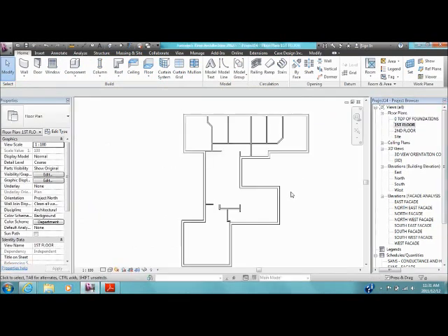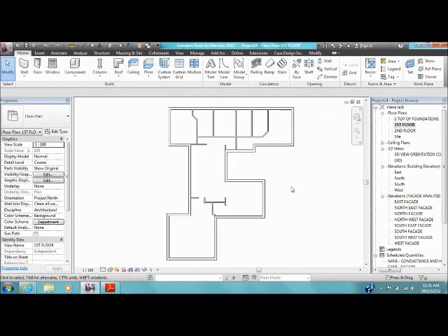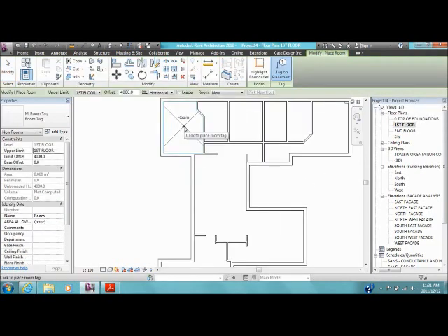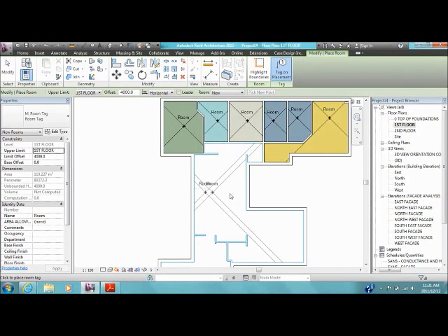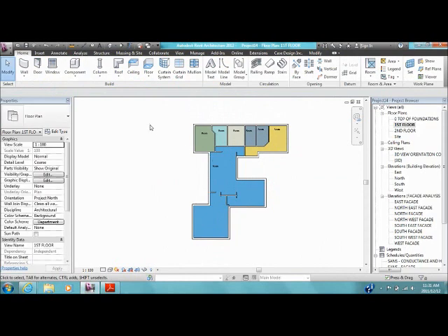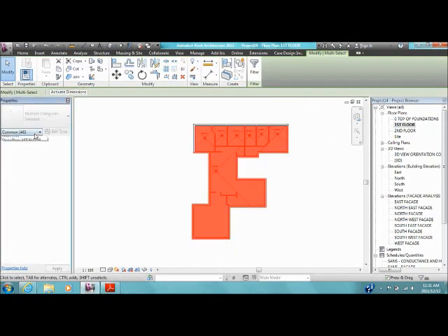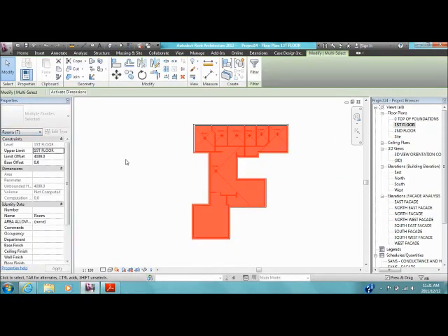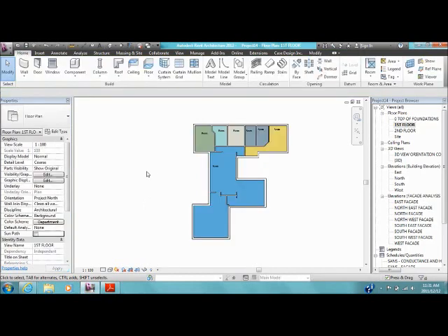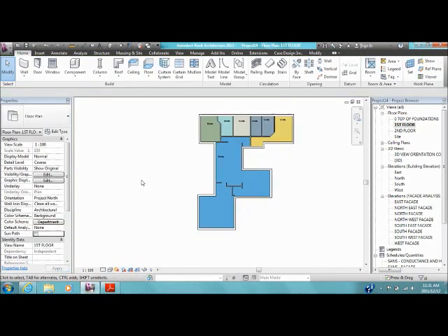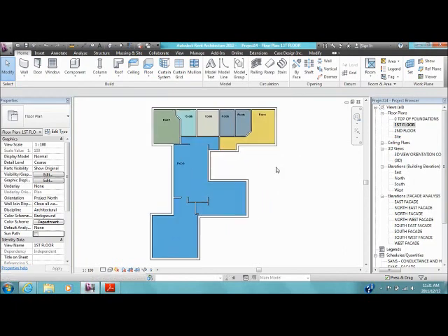Now, what I need to do first and foremost is do the calculations for the area-based allowance, in other words, for naturally ventilated buildings. I don't have to manually click in the corners of the areas to define my rooms. I can simply use Revit's automated tool. What I do need to do is tell it which zone these rooms are in, which I've just done by means of a parameter that I've created here, which currently has just one value. I've based this template upon zone 4. We'll work on the templates for all the others and easily add those additional values.